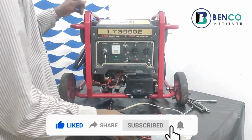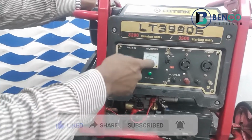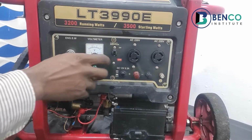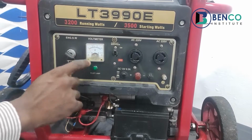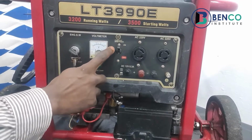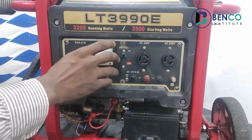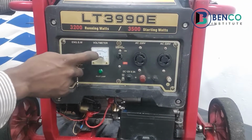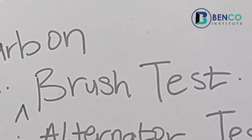And again, before I continue, another part of the eye test is this: when you put on a generator, when you know your generator is very much functional, and of course the voltmeter on the generator's dashboard works perfectly, use your eye to confirm if there's a reading here. If there's a reading here, you know you have to look for something else to work on, and certainly with other tests you'll be able to detect that. But for this particular machine, there is no reading here, so we go further with our fourth test, and that is the brush test.